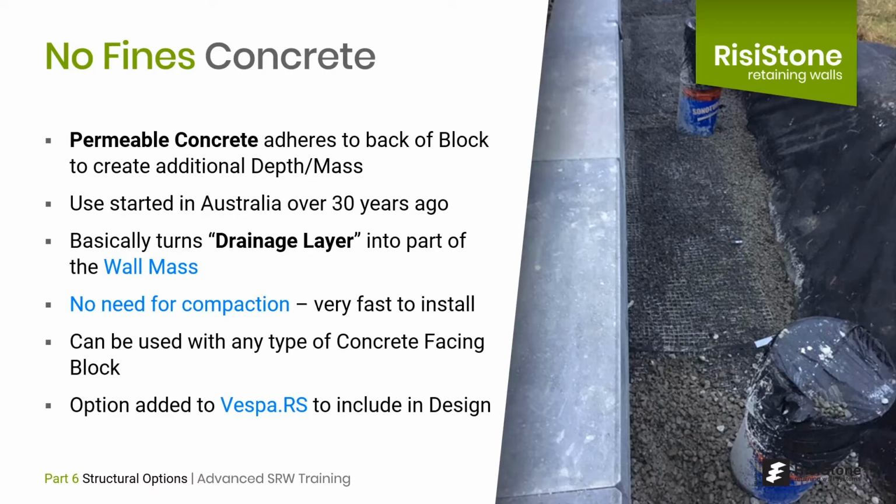The mix is poured behind the SRW unit, so there is no need for compaction, or very little. As the no-fines concrete cures, it stabilizes into a solid mass and adheres to the back of the SRW units, basically turning this drainage layer into part of the wall. As you can see from the photo, I am not totally sold on the idea that long term this mix will fully adhere to the back of every type of block. So Risi Stone has introduced small layers of geogrid as an extra assurance to combine the facing with the no-fines backfill.